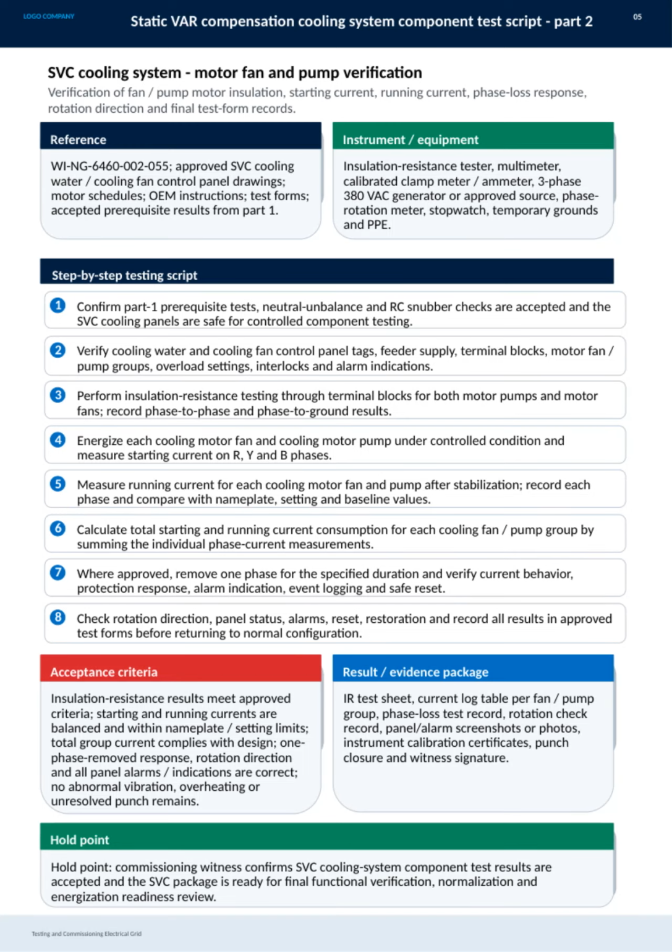On this slide, we focus on the testing and commissioning of the electrical grid specifically for the Static VAR Compensator cooling system, covering motor fan and pump verification. The key tasks include verifying motor insulation, checking starting and running currents, testing phase loss response, confirming rotation direction, and completing final test form documentation.